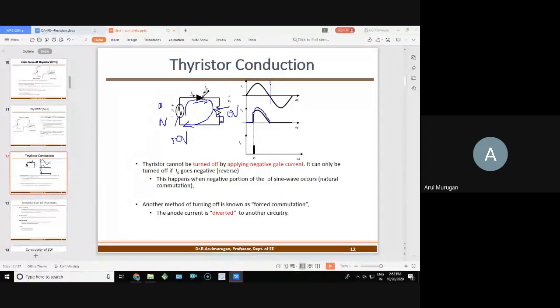Positive half cycles. Here you are going to vary the resistance, either starting from 0 or going to 0 after 30 degrees; you will decide. Here you will use the resistance method for the triggering circuit and give the power supply plus, with respect to minus, where minus is the cathode. That is the triggering circuit. It helps. Okay, the positive half cycle is okay.